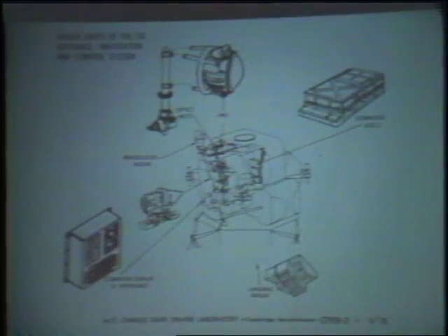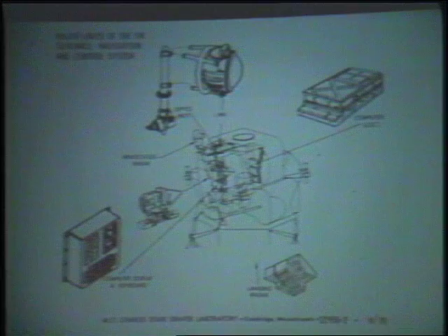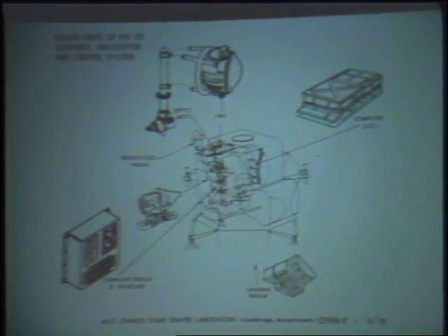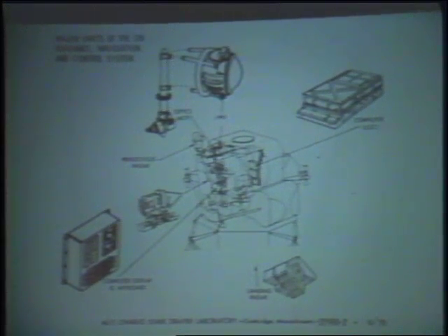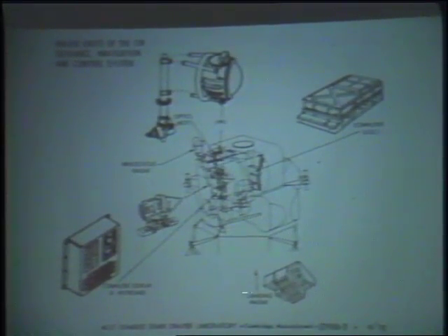In the LEM, the astronauts are standing in the position here, and the computer is mounted behind. Again, this is an identical computer, as you can see. The DSKY, also identical, is mounted down between the two astronauts where it's visible. Identical IMU, landing radar, and some other displays, and then there's a rendezvous radar, which those items make up essentially the information sensors and the computation.